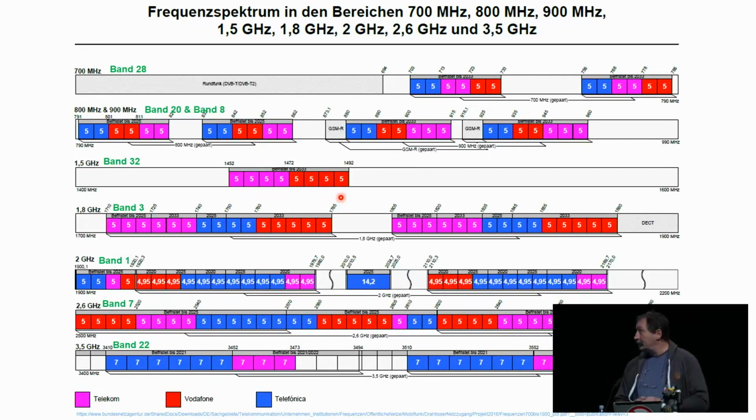If I would send in this 1.5 gigahertz in such a small device, this would interfere with the integrated GPS receiver. This is about 1.4, so it makes no sense for your device to send something there. And so this frequency is only used if we have another connection on another frequency band, and the downlink rates can be increased by using this band.